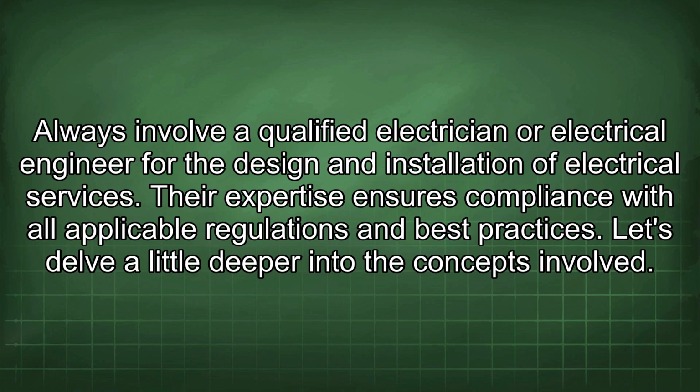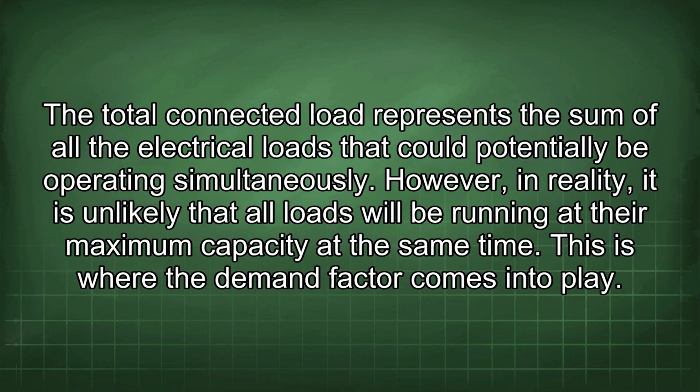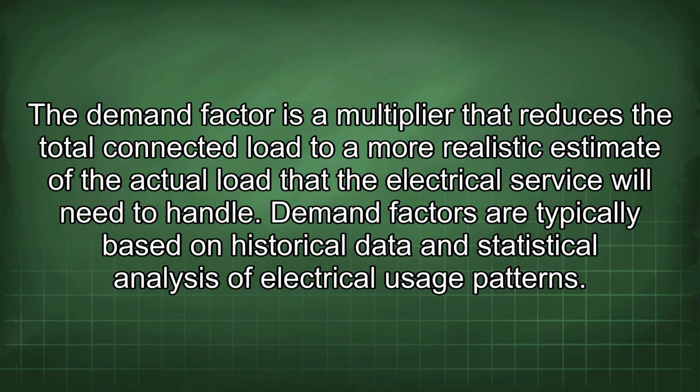Let's delve a little deeper into the concepts involved. The total connected load represents the sum of all the electrical loads that could potentially be operating simultaneously. However, in reality, it is unlikely that all loads will be running at their maximum capacity at the same time. This is where the demand factor comes into play. The demand factor is a multiplier that reduces the total connected load to a more realistic estimate of the actual load that the electrical service will need to handle.